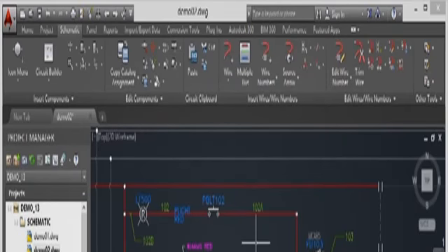It's great because it means that you don't have to keep going and looking up catalog information. You are in essence copying database information from a component that's already got it to a component that is in essence database-wise blank. It's not blank on the drawing because it's still showing here as a red pilot light, but you want to make sure that it's got the appropriate catalog information so that when you start reporting later on, it comes up in the right report with the right catalog information. So that's how you copy the catalog assignment from one component to another in your AutoCAD Electrical drawings.